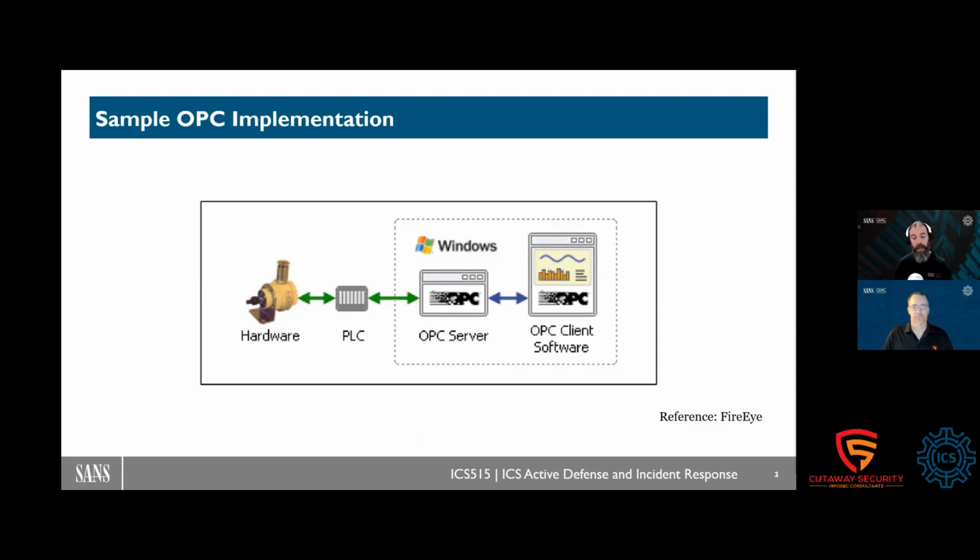And again, that's alarms, the process historian, or maybe the enterprise historian, and maybe a safety instrumented system where we want to read what's going on in the safety system and have a view of it. But obviously, we're not looking to do a lot of control there. Where we do want to write things into the safety system, we need to be really mindful of how we're segmenting and managing that interface. Sometimes that's just hardwired signals from the control system to the safety system, so we don't have any write comms back into the safety system. Maybe we have a different channel where we have Modbus writes or something, so that we're segmenting how we use the protocols so that they can't be abused in any way, shape or form.